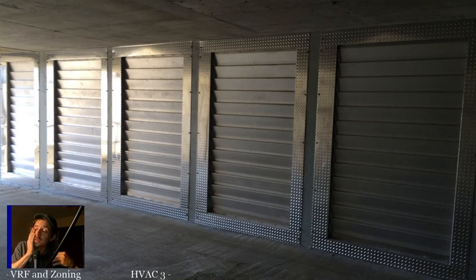The blower wheels in those mini splits, remember I told you the access for them is important, especially on each side, because some of those things you have to remove. Part of that is on certain mini splits, the only way to get the blower wheel out is through the side. A lot of them it can come straight out, but not all of them. It depends on the design of the mini split.